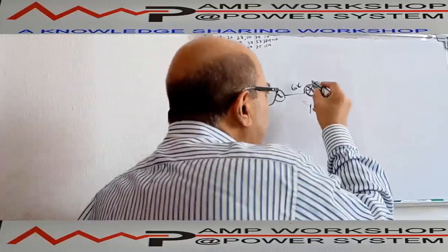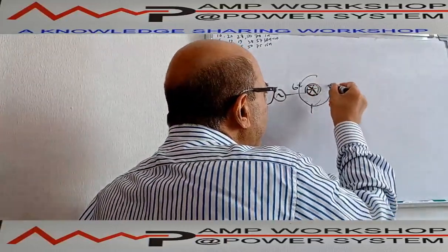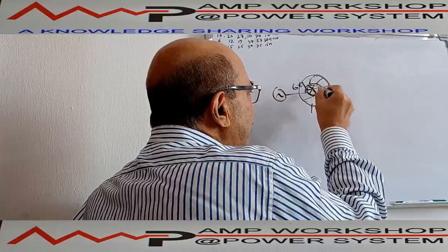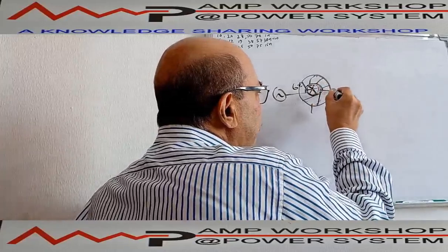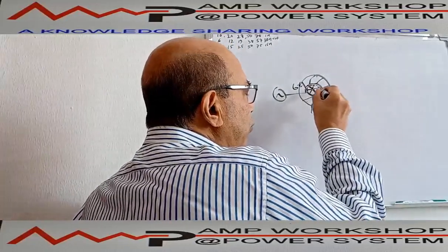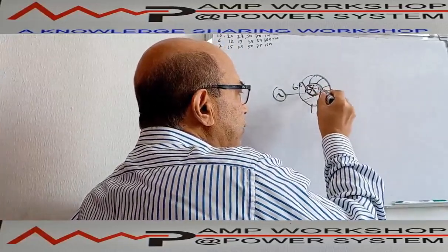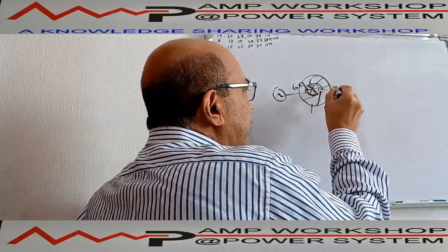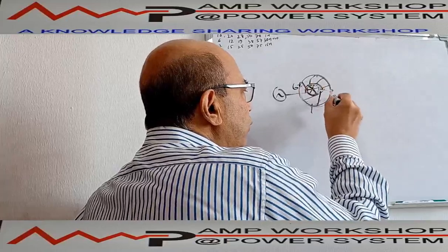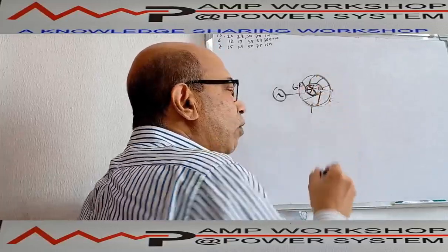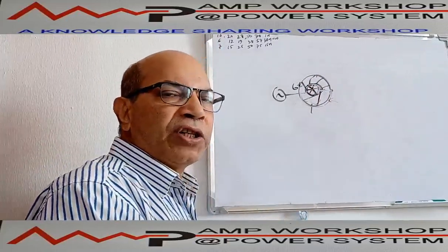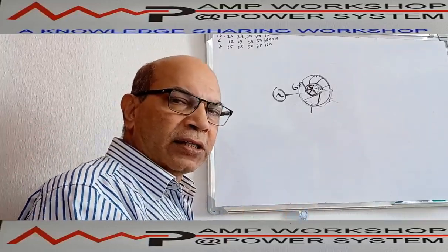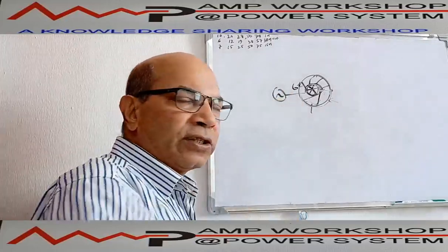So this conductor will be wrapped with an insulating material so that this 6.6 kV voltage will not come to the surface. The surface voltage will be zero. We have to decide the insulation thickness in such a way that the 6.6 kV voltage will be diminished over this thickness. So at this point there will be no voltage. So the conductor shall be wrapped with some insulating material to avoid the voltage on the surface. So the second thing is the requirement of an insulation system.